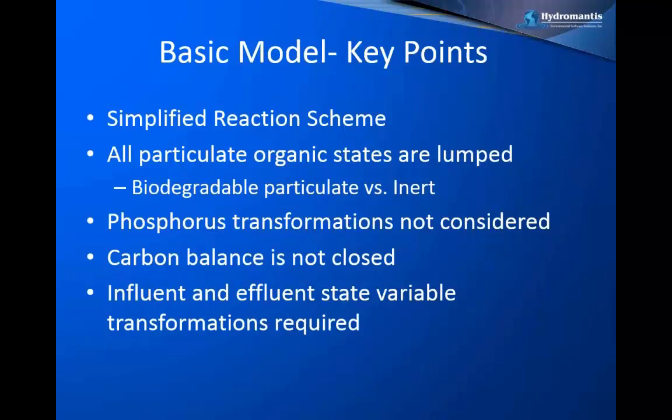Let's look at the key points for this model. It's a very simple reaction scheme, but being simple also has its downsides, because all of the organic states, for example the inert organics and the biodegradable organics, are lumped into one single parameter, VSS. From plant to plant, there might be a need to calibrate or change the value of the degradation constant if we are using just one lumped parameter without giving consideration to the relative fractions of biodegradable and inert substrate.